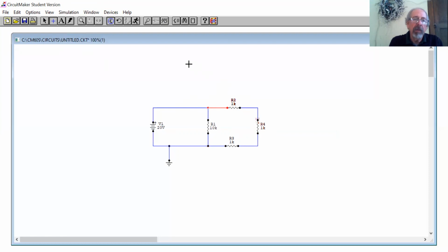And you can move components around, by the way. Let's go back to the cursor arrow. If I take this resistor and get on it and use my up key, I can move it around, and my down key, as long as it's highlighted. Of course, I could just drag and drop it: if I left click it, I can move it up and down with my cursor arrow. Now, these are 3 in series, and those 3 in series come up with a 3K total, which would be in parallel with a 10K.